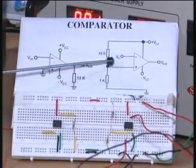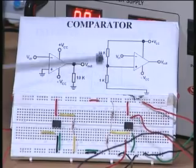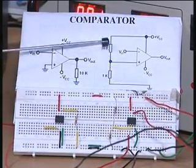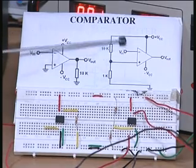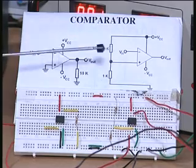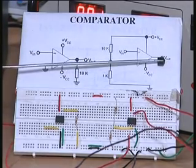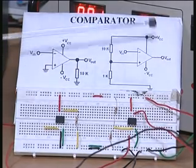To pin number 3, which is the non-inverting input, I put a potential divider with a 10k and a 1k, and I have connected the midpoint. This will be approximately 1/10 of the voltage that I apply for VCC. If I apply 12 volts, it will be around 1.2 volts or so. That will be the threshold voltage. Now we have to monitor the output voltage. For monitoring the output voltage, we will use a multimeter.